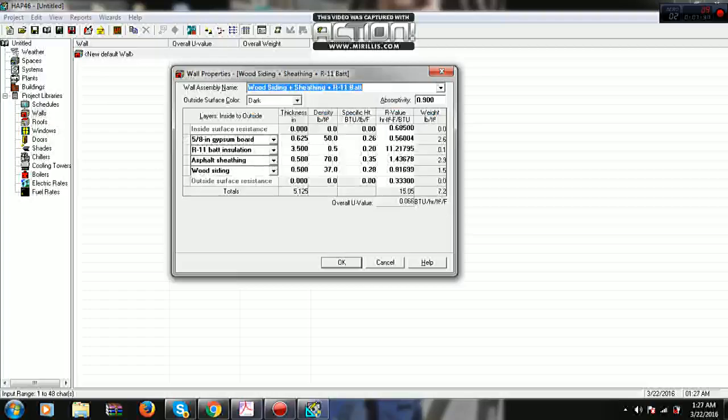Okay, but a very important thing here is that in the practical scenario, most often the architect may not give you this information, or he might not have this information in the initial stages. So there will be standard U values given by the architecture, or you might know them from your previous projects.